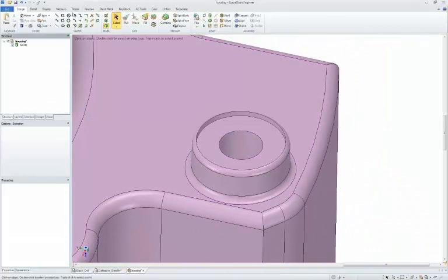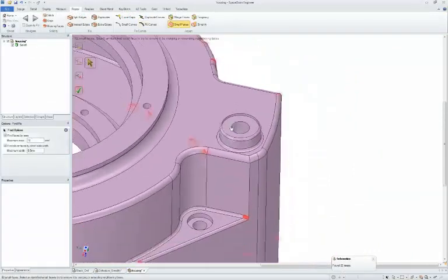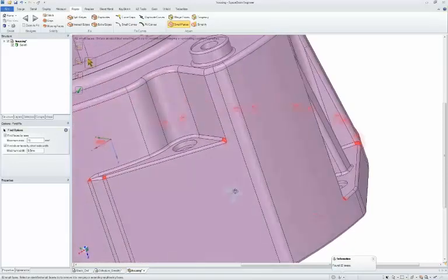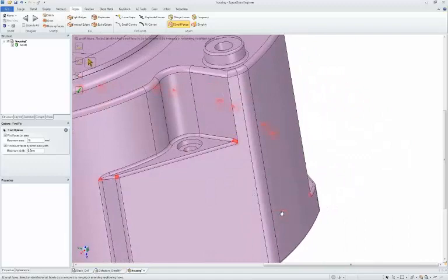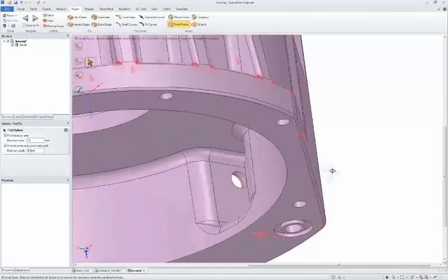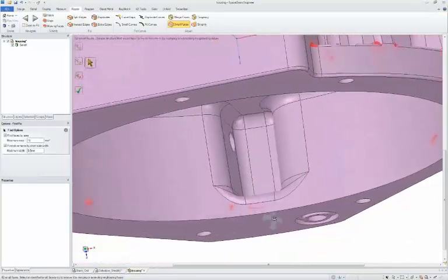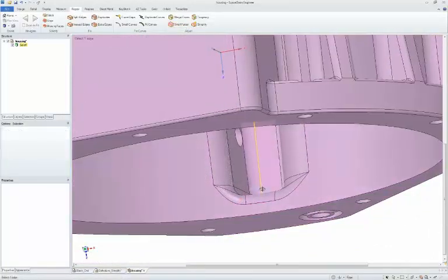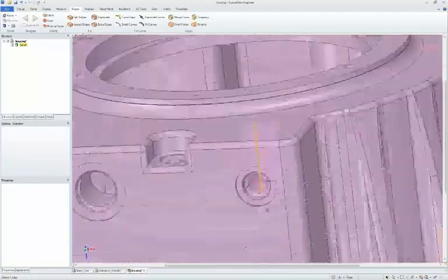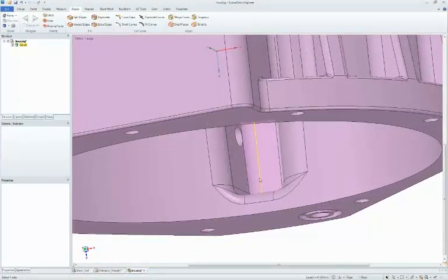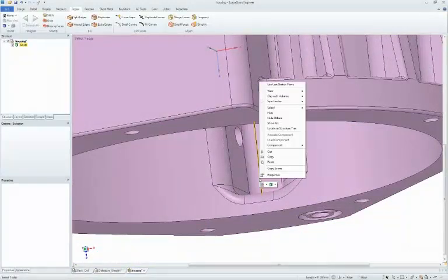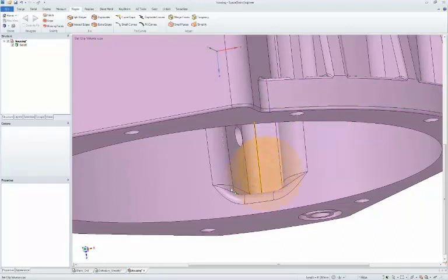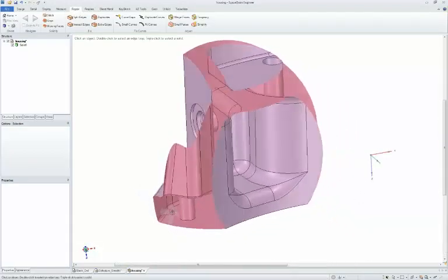Another thing we'll get rid of and start to look at is, let's say I go back to that small face tool, starting to search for them. I mean, most of these look like they're on the outside of the part or the model, but this example here, you'll notice, you can see there's something kind of inside that part there. This is something that's really cool about SpaceClaim. There's not a lot of good ways to see inside of a part when you have all these other faces kind of blocking the way. What SpaceClaim allows you to do is, even on complicated models with openings that you can't get into, you can clip that model that's there. I can just create a clipping volume or a clipping area, and notice everything outside of that is clipped away.